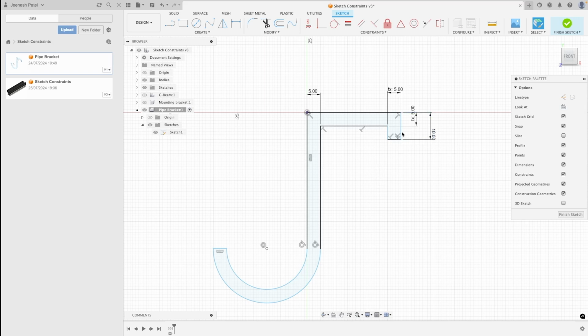If we ever get confused on what constraint has not been applied, we could simply click and drag on the blue line and see what changes about the object. This will inform us on what constraint is yet to be added. As you can see, the position of these two lines is yet to be fixed. We can introduce a dimension to fix the position of these two lines.